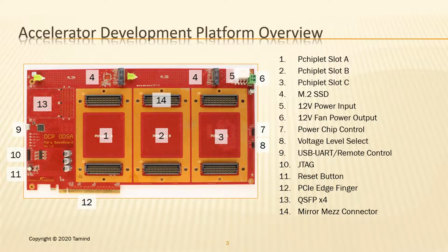And then you can go into these boards remotely using a USB UART. We have a USB UART setup, and that is powered independently of the board. So you'll be able to do a remote execute or whatever you want to do, or even shut down one of the platforms if you have support from that platform. The pitchlet, you can even shut it down and switch it back on through the GPIO control, and that is powered independently through USB. And then we have JTAGs, reset.